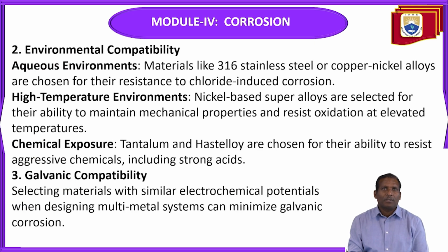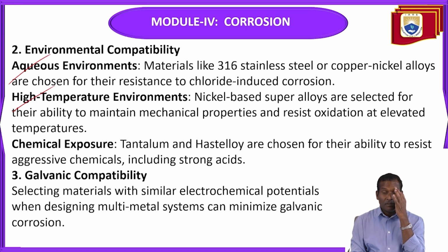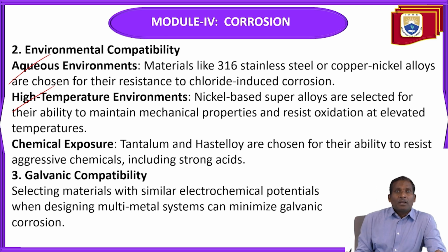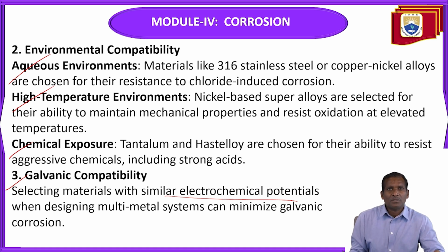Next, environmental compatibility. Aqueous environments and higher temperature environments, chemical exposure, and galvanic compatibility. Selecting materials with similar electrochemical potentials when designing multi-metal systems can minimize galvanic corrosion. So whenever tantalum and nickel alloys are chosen for their ability to resist aggressive chemicals, including strong acids.